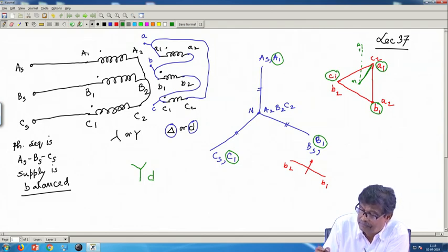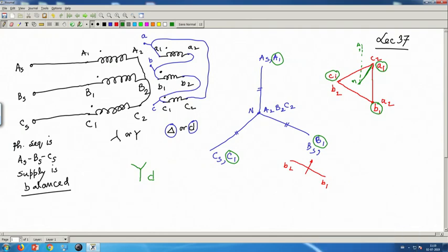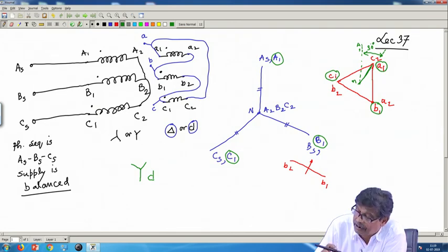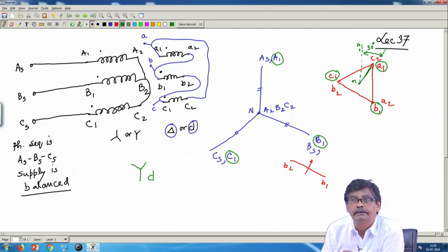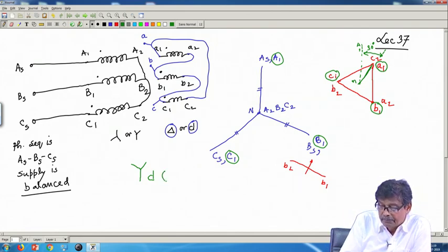You should not get confused that capital N and small n are connected. No, small n is not there in fact. But anyway, that is the A1 phase vector, that is vertical. So, I find that this voltage lags the phase voltage with respect to the neutral on the primary side by 30 degrees. And I then write it as lagging, so maybe minus 30 degrees I will be telling it.